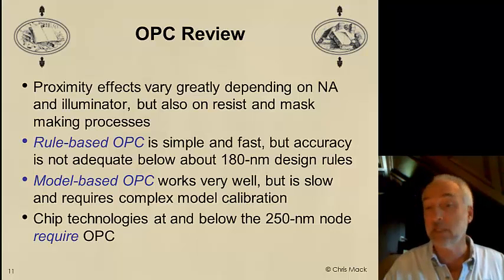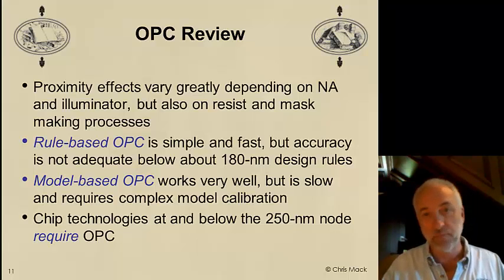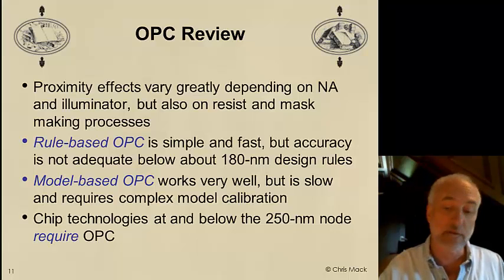At chip technologies at and below about the 250 nanometer node, you simply have to have OPC. None of our chips would work today without OPC. It's an absolute requirement in terms of making our lithography work at these very small dimensions.